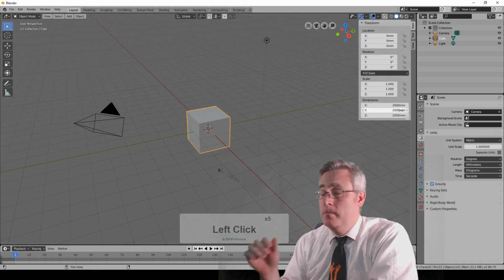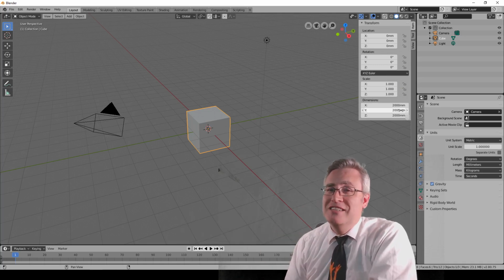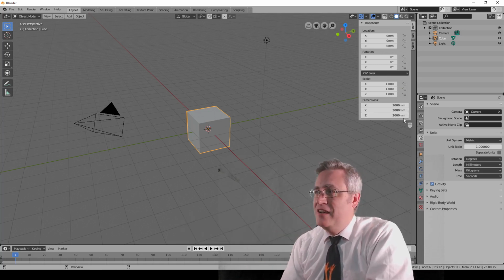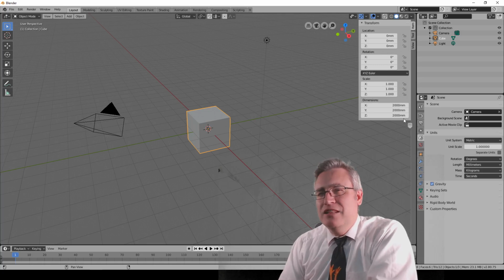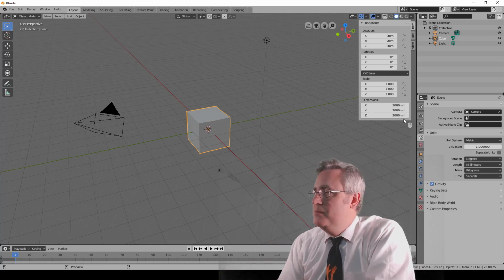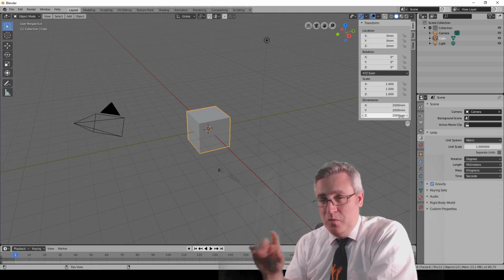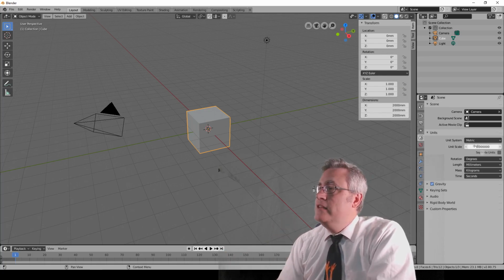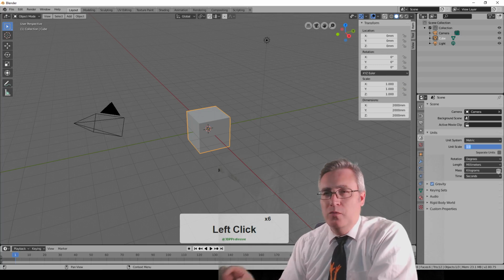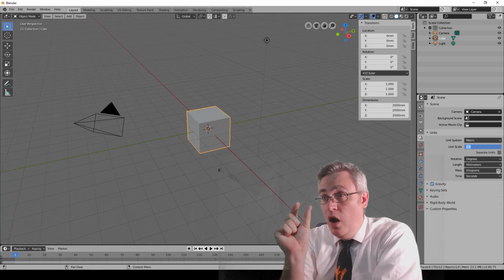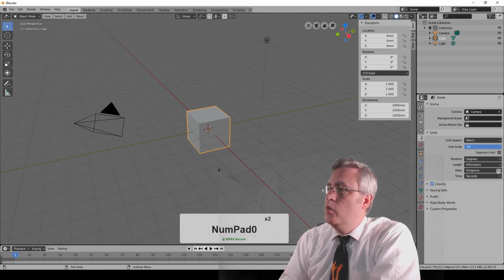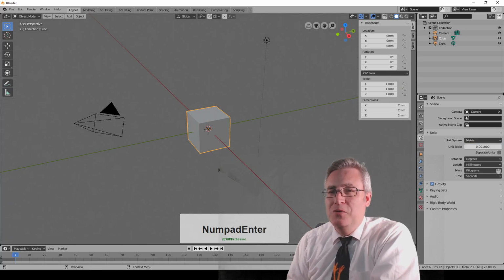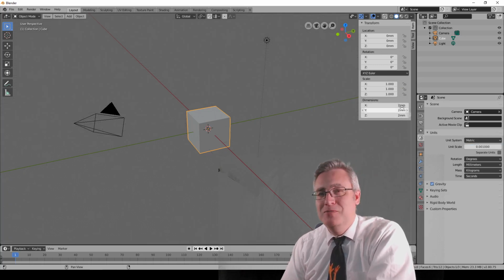Now look at our cube. It is now 2000 millimeters by 2000 by 2000. It's still 2 meters, which is closer. It's at least expressing it in millimeters, but we want that to be 2 millimeters. So we need to change our unit scale, what Blender thinks of one as being, to 0.001 metric unit, which means now this cube is 2 millimeters by 2 millimeters by 2 millimeters.